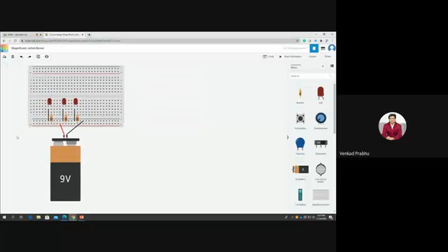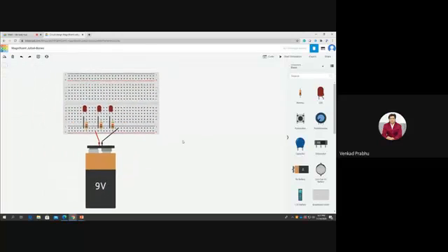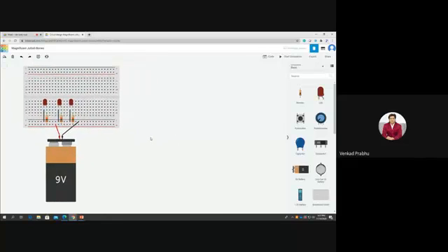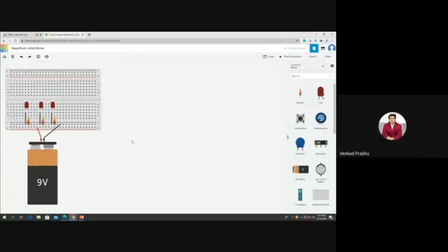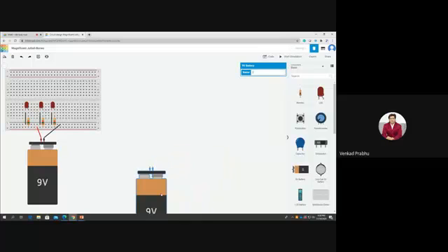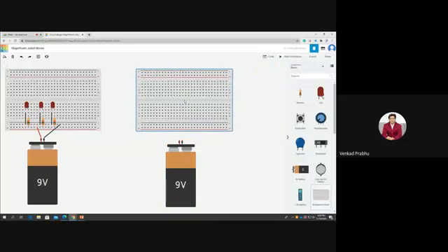So I'm just moving this side. If you click outside of your work area and move your mouse, that entire scenario will get moved. So I am moving this to the corner, and again I need a battery to demonstrate another method of using the breadboard. I have used the devices in the inner part of the breadboard. Now for the outer part, take another battery, use the R key to rotate, and take a small breadboard. I am going to put it here.